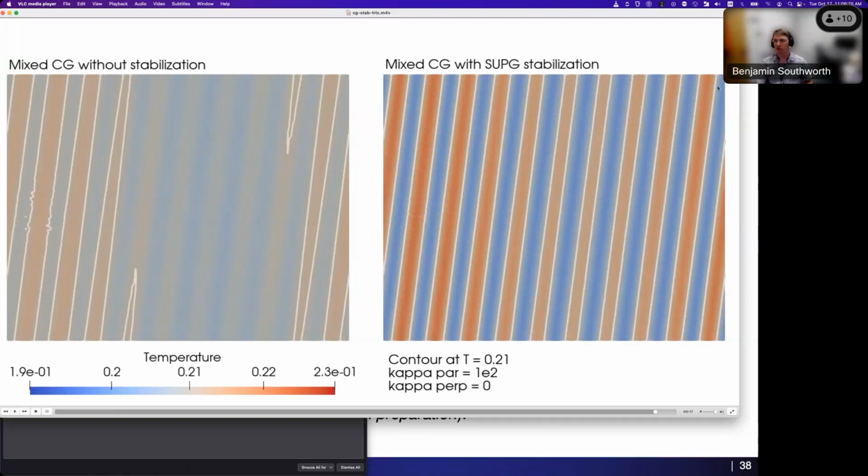Okay, so unsurprisingly, how can this work, and how well will it work if you have curved elements and high order discretization spaces? So I think it would work well, and there are multiple pieces to that. The purpose of this in the first place was to assume no structure of the magnetic field lines with the mesh, and so in that case, going to fully unstructured, going to curvilinear, going to anything like that from the solver perspective doesn't matter. And from the discretization perspective also doesn't really matter.